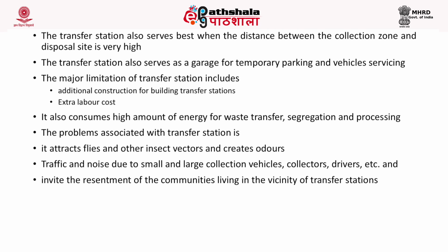The problems associated with transfer stations include that they attract flies and other insect vectors and create odor because they act like a temporary storage site. Also, traffic and noise are created when vehicles enter the transfer station for unloading and reloading. Third, it also invites resentment from the communities living in the vicinity of the transfer station.